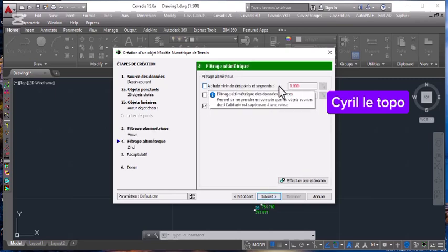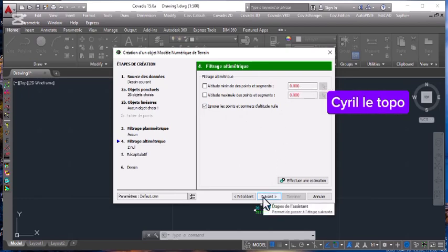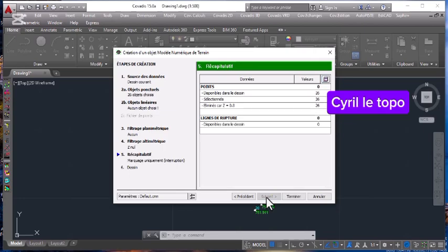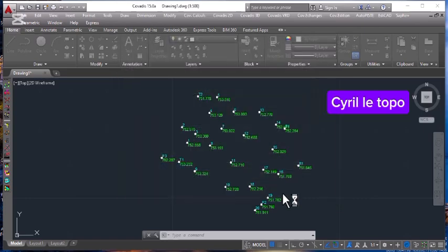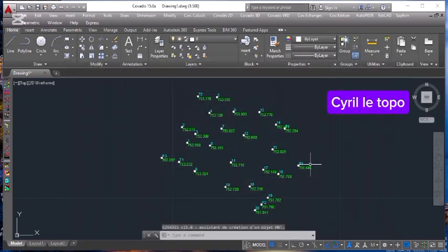Here we observe that our point has been considered as 0 point. That means in this case, we cannot calculate our digital terrain model because our software considers our points as 2D points, of which we have done a 3D survey. This happens at times. You see, we are not able to calculate a digital terrain model in this case. What are we supposed to do?